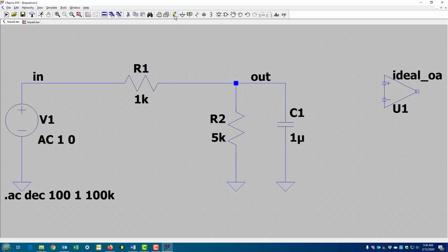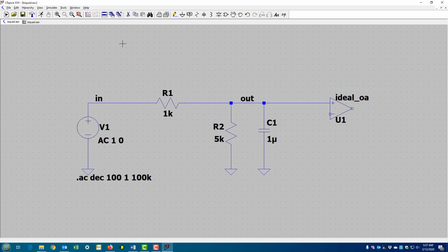So now we're in position, and let's just do a little feedback here. Maybe we want to put a little bit of gain here. So I'm going to get a resistor. Let's just put a resistor here, and do Control R and get a resistor there. Do a little ground, right here. Let's just wire this up. Okay, let's do a gain of 10. And now we have a new node here.